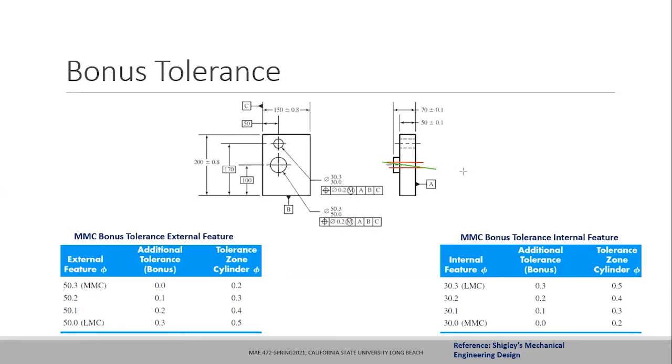How do you measure the orientation of the axis? As I mentioned before, a cylindrical object is held either in the chuck of the lathe machine or the spindle or chuck of a simple spindle that is basically going to the datum feature simulator. That will help you to measure the perpendicularity of the object.